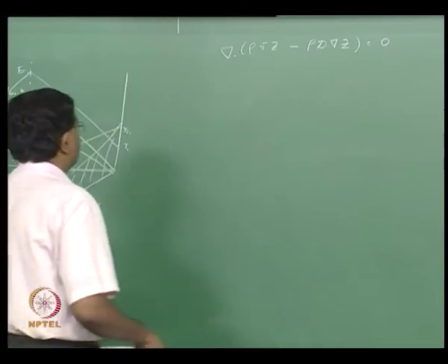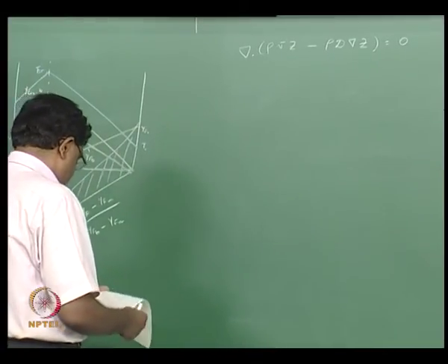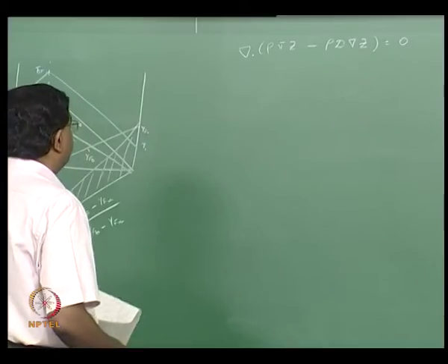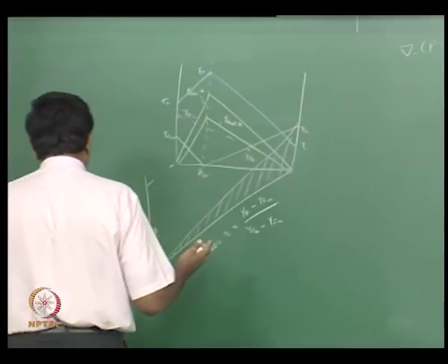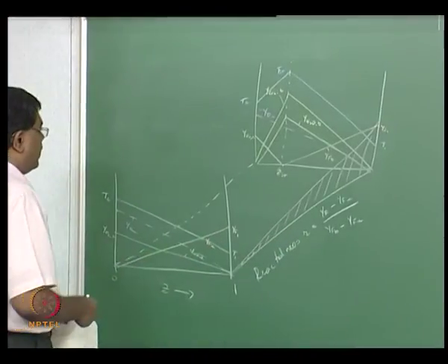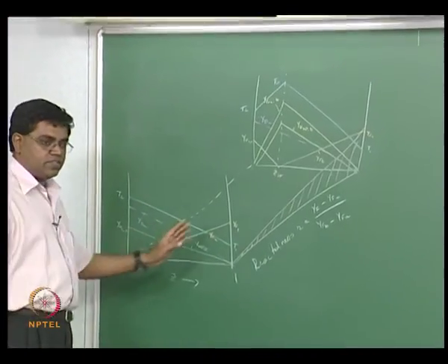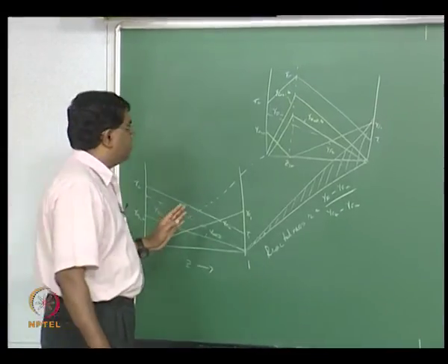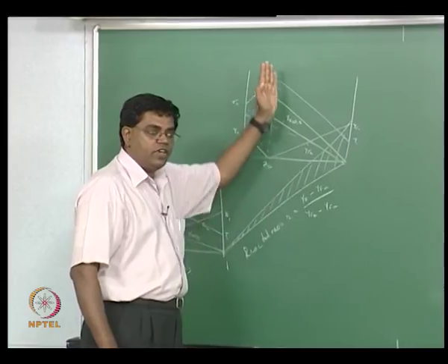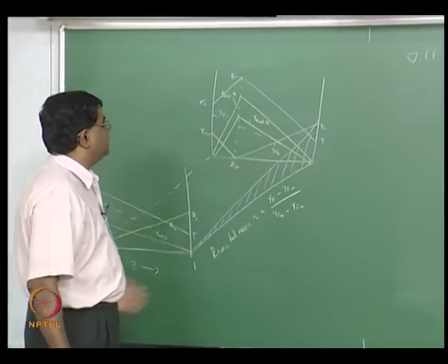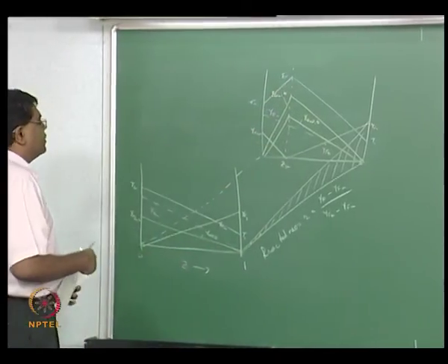So we just write this out as it is, and then the other thing that we need to do in order to actually look at the structure of the flame. So this is okay as far as the infinite chemistry approach is concerned. What we talked about in the Burke-Schumann problem was that this is like a sheet that corresponds to infinite chemistry, and on either side you have these things dropping and varying correspondingly.